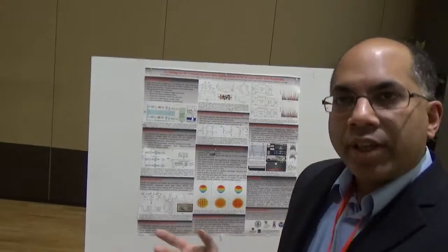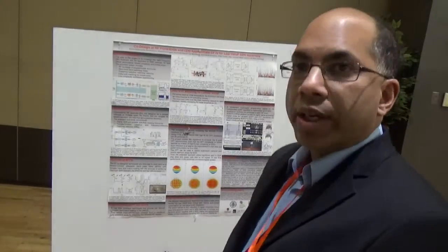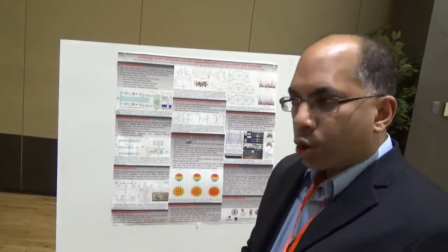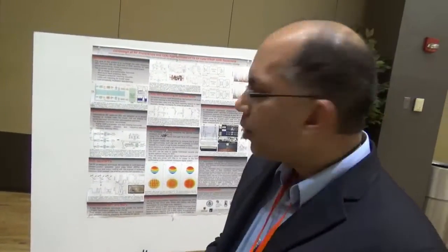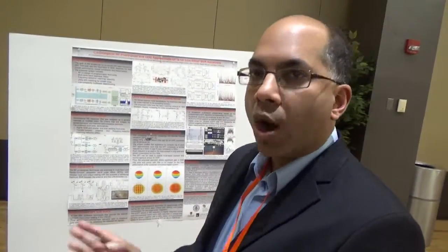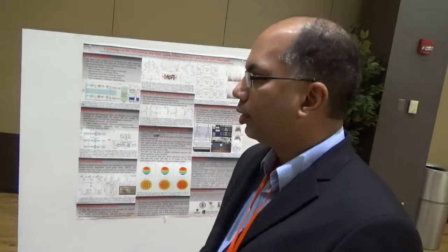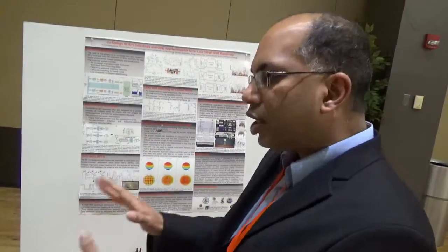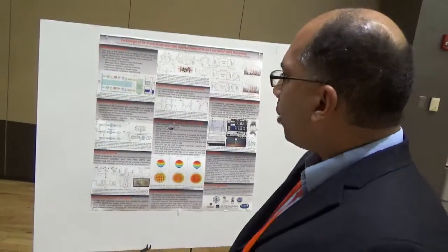So, using an FFT as an example, I'll explain to you the approach. An FFT is a fast algorithm for implementing a discrete Fourier transform, or DFT. A DFT, if you want to build directly in hardware, will require about n squared multipliers for an n-point transform, and an FFT reduces that from n squared down to about n log n. It turns out that by allowing a little bit of error in the computation of the FFT using approximate computing, you can get rid of this n log n bound and make it smaller. We can make it order n. That reduction of a factor of log n becomes very significant for large n.